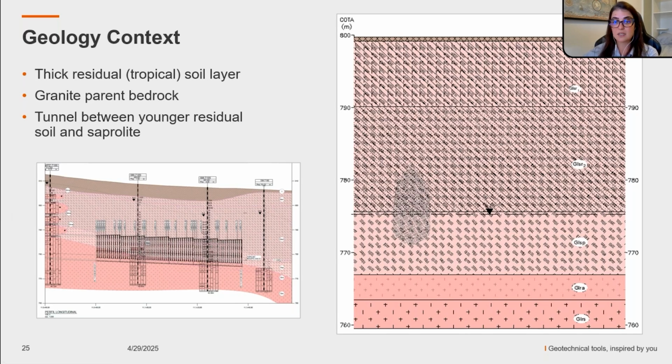And in this type of project, soil parameters and constitutive models are generally defined based on SPT data and the prior experience of design engineers. So typically we use the Mohr-Coulomb model for the soil layers, while the Hoek-Brown model is more appropriate for the rock.